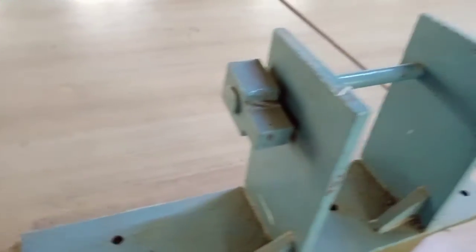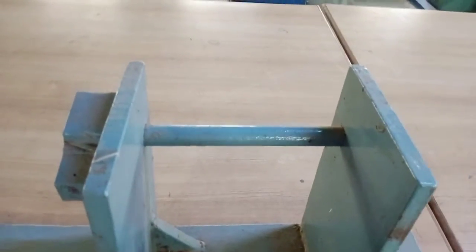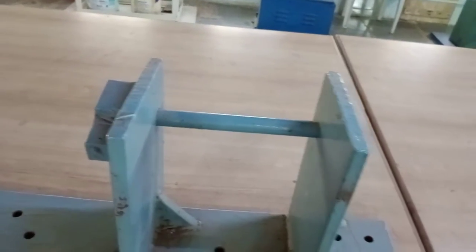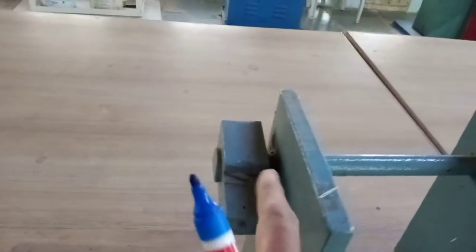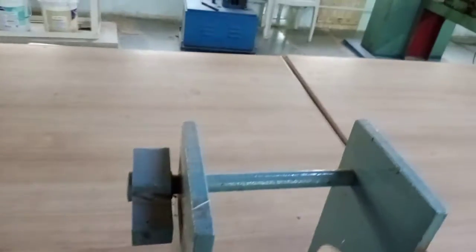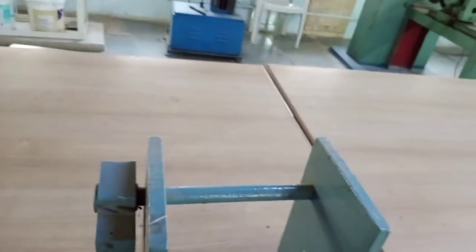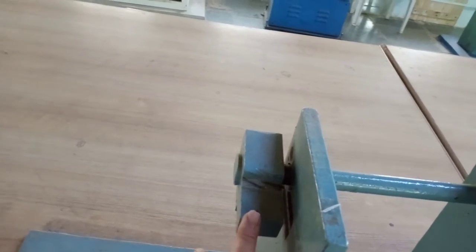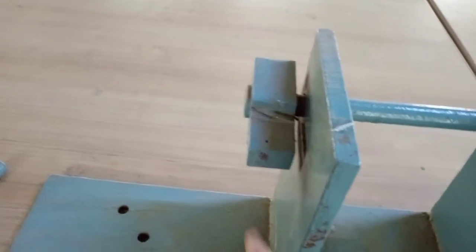And theta, as I am showing, we are getting from here through the dial gauge, by L. L is the length of the shaft. From this point to this point we have to take it. Here everything we know except the G value. So when you are providing all these values for a particular rotation, a particular movement of this dial gauge, as it is rotating downside, the force we can calculate. What is the rotation, the vertical distance it is traveling, we are knowing it. When we are knowing this vertical distance, we are knowing the value of theta. Once we are knowing theta, we can find out the torque.